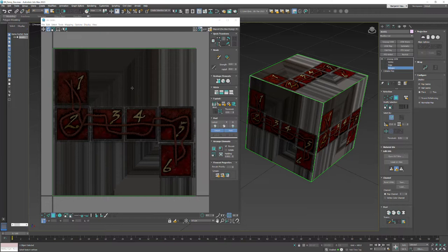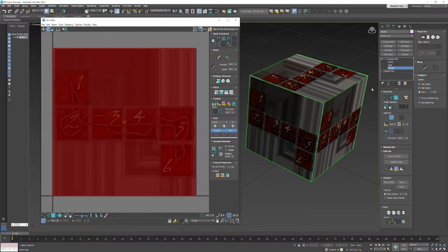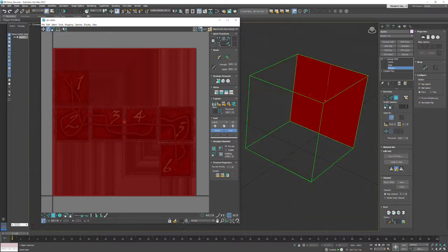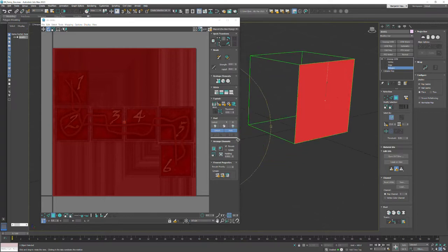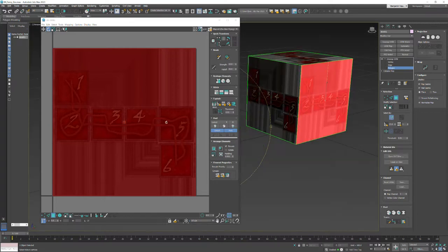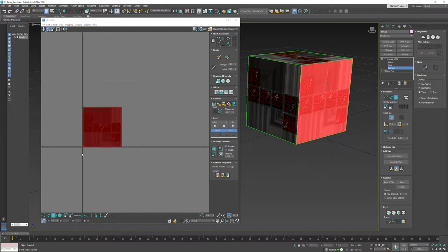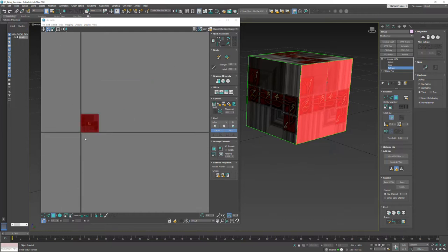All right, so as I come in here, if I just click in this space, something gets selected, but what is it? You can see there's a little X, Y, and Z. If I hit F3 to go to wireframe, you see, okay, there's a polygon there. Let's click on orbit, orbit around, hit F3. So effectively what happens is the generate UV coordinates is just a default setting. It just gives you a very basic set of UVs. Every one of these surfaces is mapped to what we call 0 to 1. See these two lines? You have U, which goes across, and V, which goes up and down. I like to remember V by just thinking vertical. That's not what it means. All right? There's no hidden meaning here for U and V in the UV coordinates.